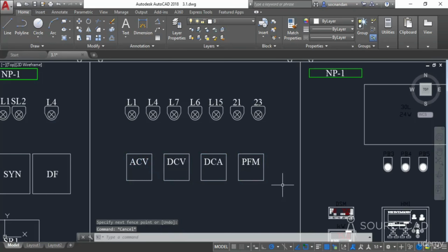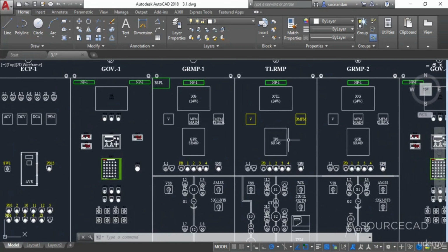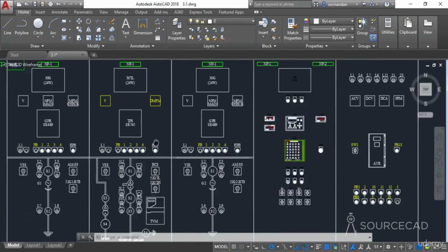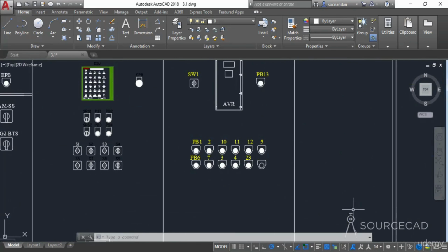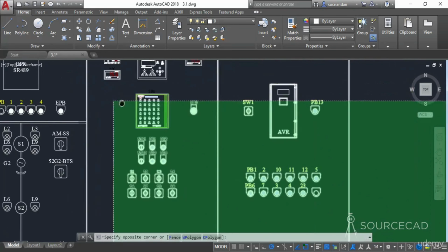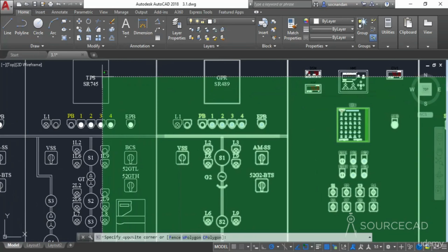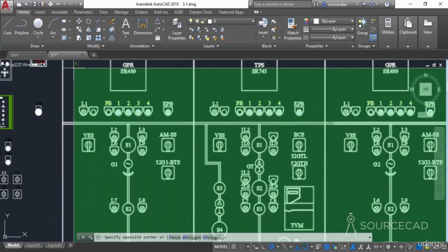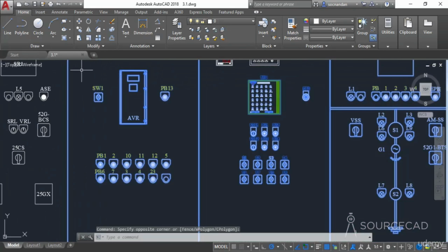In the AutoCAD 2018 version, AutoCAD added an off-screen selection, which is helpful for selecting long geometries. Let's say that we want to make a selection by zooming this drawing, and we just want to start our selection somewhere from here. Now we are including the objects in our selection set, and along with the inclusion of objects, we are also moving the drawing towards the right. We are scrolling it, panning it here, and now we are including many objects. Now let's click here.